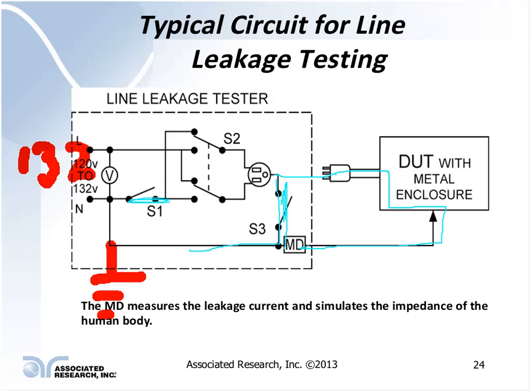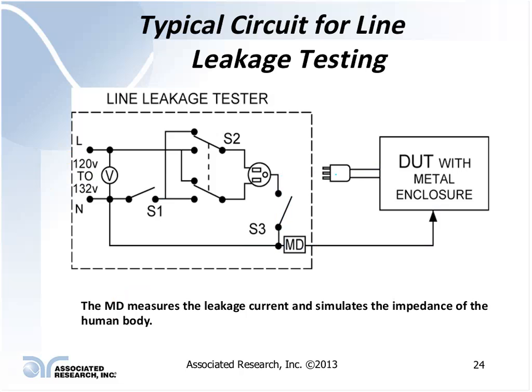When the product is operating, I see different leakage potentials depending upon the input polarity, based upon the design of the circuitry within the product itself. So this test is designed to test how much leakage current is actually flowing through the product under different conditions.